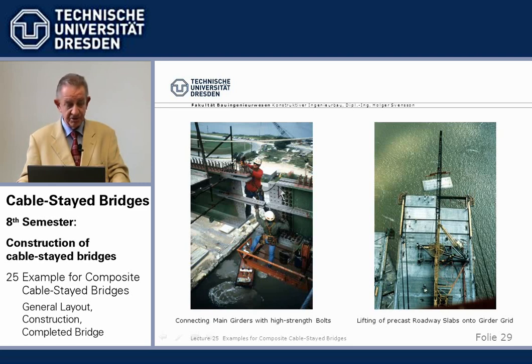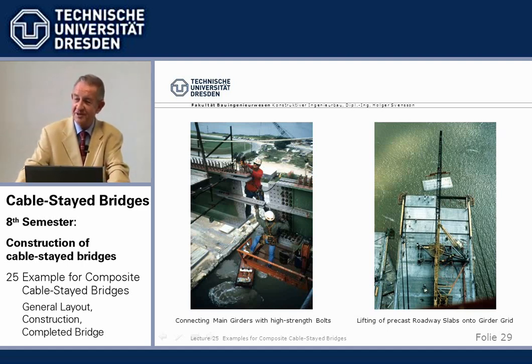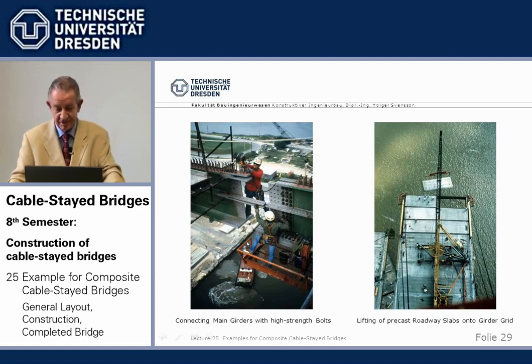And as I told you, no side welding in the US. We do it the good old way, cover plates and high strength bolts, and strong men standing up there 50 meters high with a wrench, pulling it together. It's hard for you to find something like that in Germany, where it's all welded, but there it's the method of choice. And the steel workers are a strong part of the people on site.